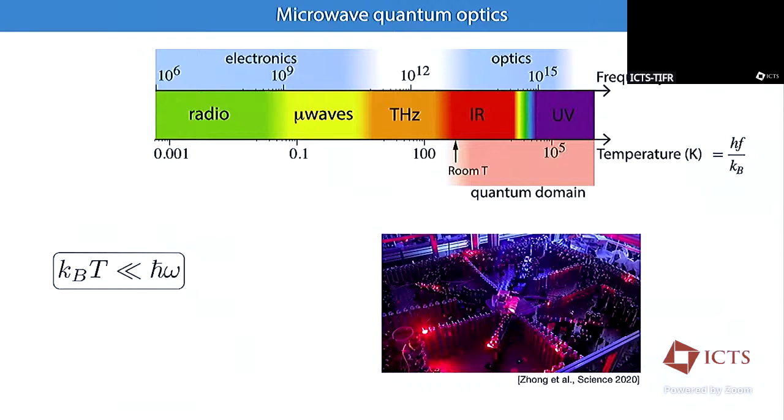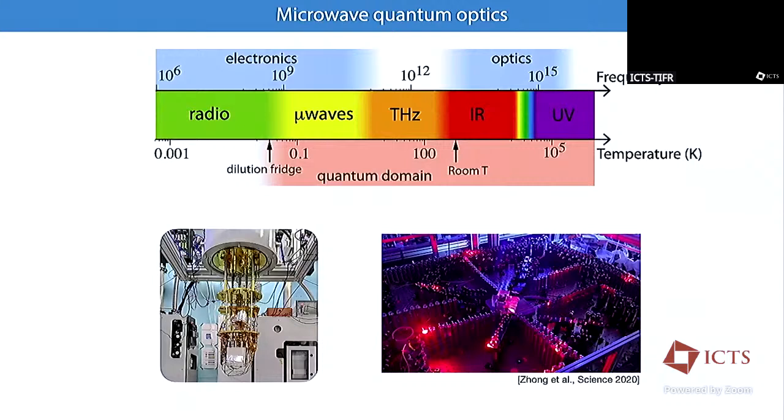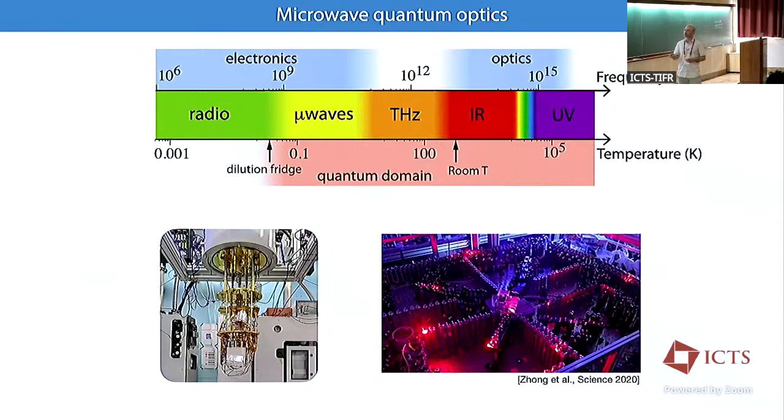In a few gigahertz mode, you see it's well below the room temperature limit, and so we need to use commercial equipments, which are called dilution refrigerators, like in this picture, to reach an environment at a temperature of about 10 millikelvin. And at 10 millikelvin, indeed, a few gigahertz is well within this constraint. And so, likewise, by just thermalizing to the environment, it's for free at these temperatures. And so it's not for free; it's for 400 kilo euros, let's say.